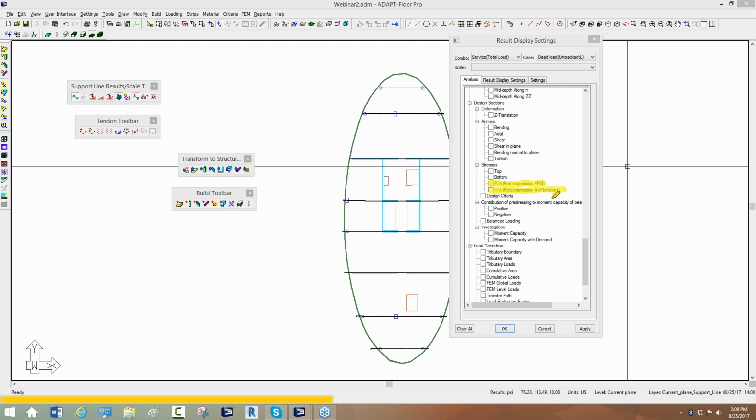So the second option just basically ignores the axial buildup in the slab, or loss of precompression in the slab, I'll say, and it checks the precompression, assuming that outside of the model in your detailing you take care of the restraint issue. So that's why we have two different options here.